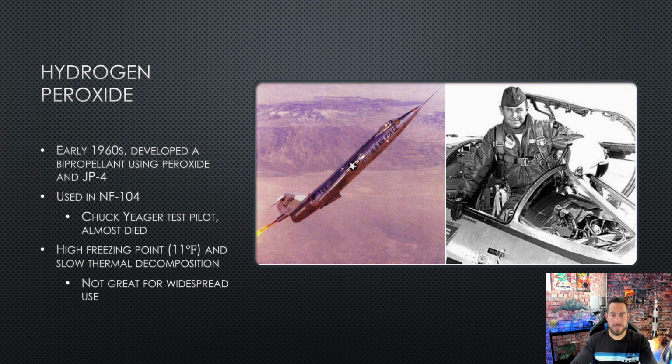Basically, I'll just cut this short, but it had rocket thrusters in the nose too. Once it got up into the high atmosphere, you couldn't nose down. When you push the control stick forward, it would typically cause the horizontal stabilizers, or the ailerons and the elevators, to pitch, and so it put it back down. But in the high atmosphere, you can't do that because there's not enough airflow. So they had rocket thrusters in the nose, which when they fired would put the nose back down, and then you could come back in and get your descent profile in place.